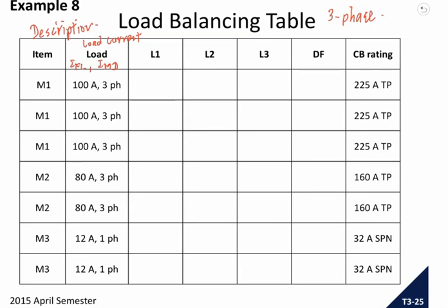You then have your L1, L2, and L3, to allow you to space out the different loads. And of course, as a reminder, your diversity factor. So in this case, we are trying to fit all these loads across the three phases that we have as a supply.